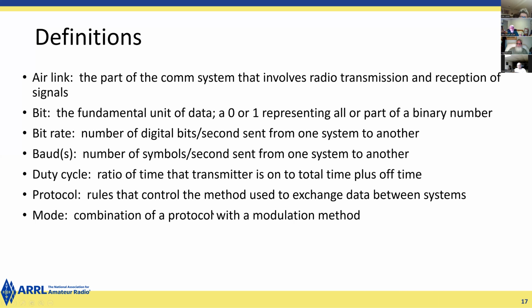The mode is the combination of protocol, as I said, with the modulation method. We went over modulation methods last week: single sideband, phase modulation, and something called frequency shift keying, which I'll show in just a moment. There's phase shift keying. There's something called spread spectrum modulation, which we may not touch on.